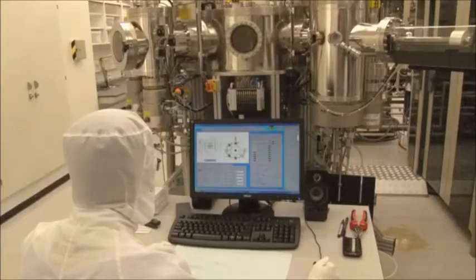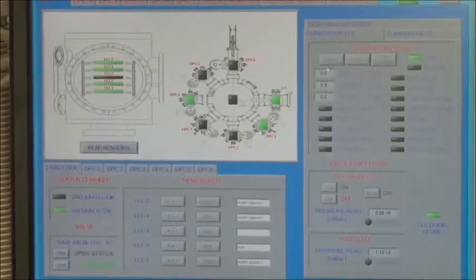Typical precursor gases in the deposition plasmas are silane diluted with hydrogen. An RF bias between electrode plates generates a plasma. The silane is dissociated and the silicon containing radicals and ions are deposited on a substrate. Adding diborane or phosphine to the plasma makes the films P-type or N-type.